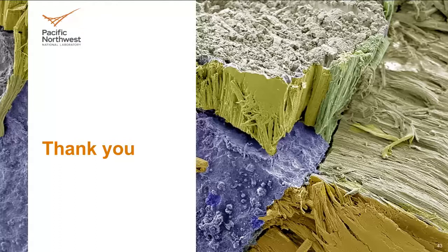So in principle, we will not require proppant, because if there is a slight displacement, and again, this is just what we observe, it hasn't been proven, we observe the material post-mortem, as well as right after we stimulate, we measure the conductivity, and the values of conductivity using water for the rock samples fractured with StimuFrac CO2 are similar to the value of conductivity post-mortem.